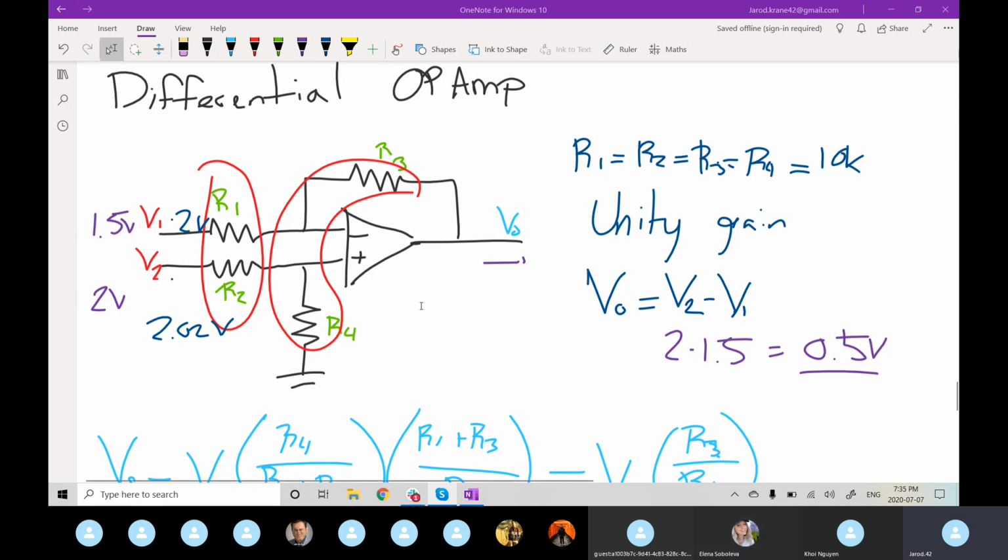Yeah. So you wouldn't want to feed this 2 volts and then have stuff running at 5 volts. You wouldn't want your output to be 5 volts and use that to power your circuit, because most op amps can typically only source hundreds of milliamps. They're not good for sourcing the couple of amps that you would normally need.